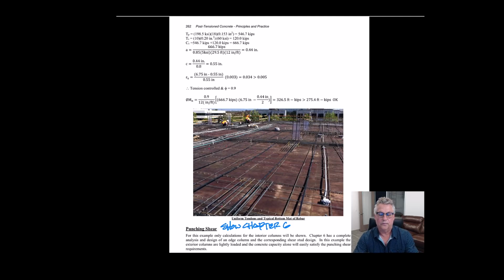Okay, so we've looked at the slab for flexural strength. We provided minimums first, top, checked the top steel flexural strength capacity using the FPS equation. We did the same on the bottom. We found the different minimum requirements on the bottom, calculated the strength associated with that, and in both cases we were substantially greater than the demand moment in those slabs.